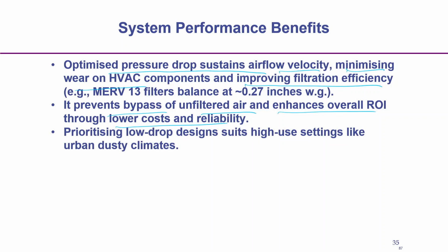So, prioritizing the low pressure drop. Low pressure drop means there will be a more porous structure; only then can we get the lower pressure drop. So, higher air flow, but which should we do? Should we go for lower pressure drop or higher efficiency?